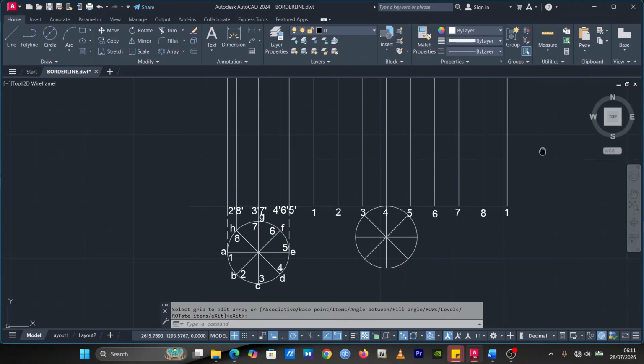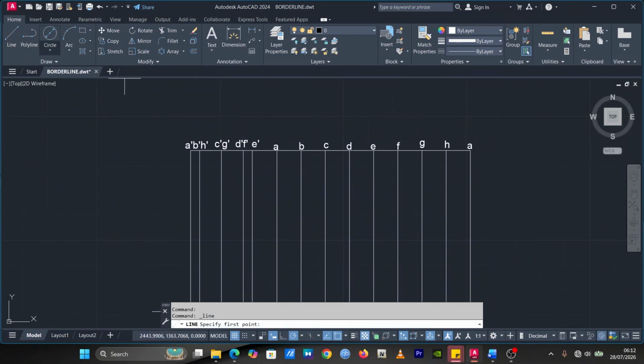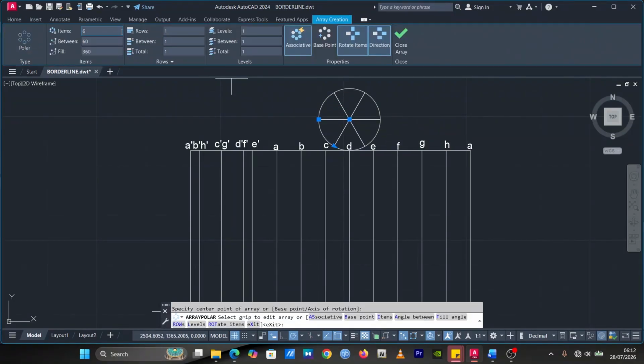We do the same thing for the top. So the top we are going to use D. So distance of 12.5. Then we draw with a diameter of 25. We clean this line. We hover for our center over here. And then from here we select, we move to polar array, we click on the center, we need 8, then we have this.